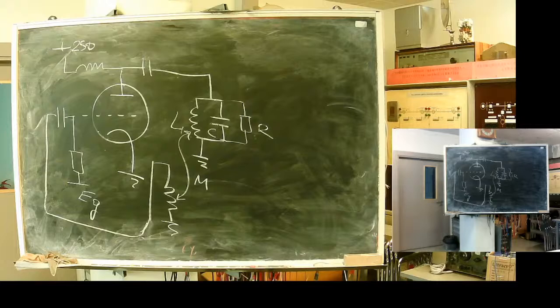And Professor, capacitance is because of that gap between the wires, right? Yeah, the higher the gap, the lower the capacity. If wires are like this close to each other, then the voltage between, like here, we have quite significant capacitance, wire to wire. And it means partial resonances, small resonance contours at high frequencies. And Professor, every gap will have its own resonance? There will be a very complex system, each turn against turn. So a turn with its capacity creates one contour, and one layer of the coil to another layer, another. It will make a very complex picture. Quite disturbing.